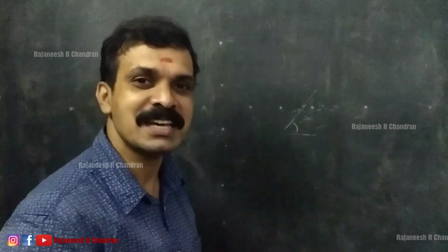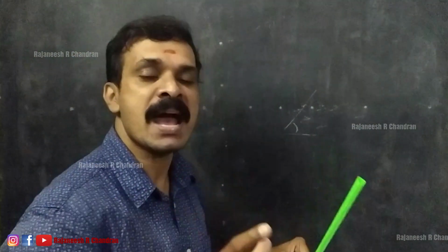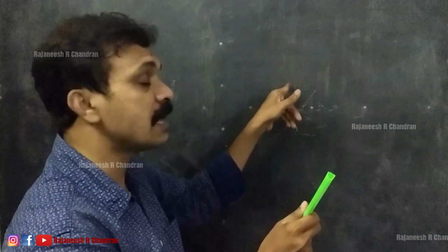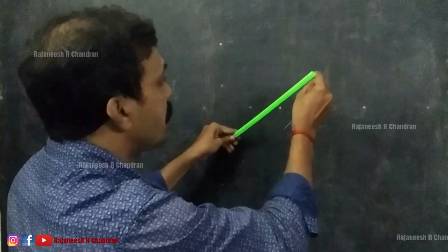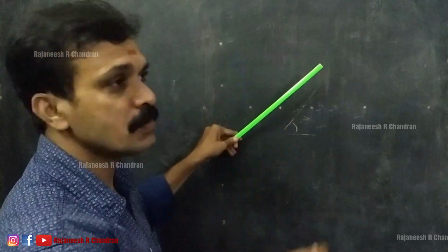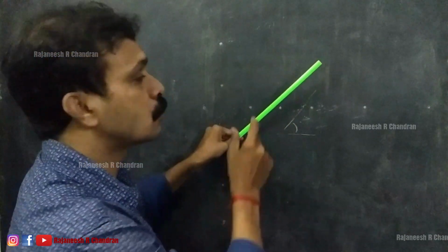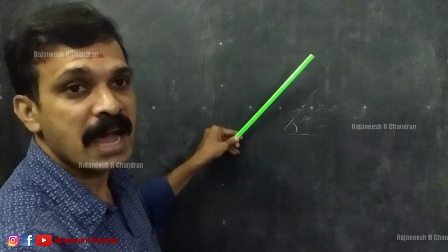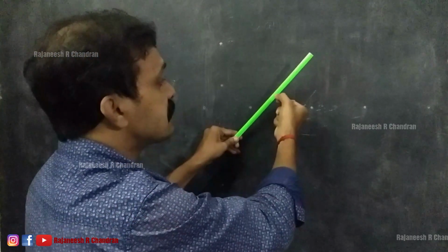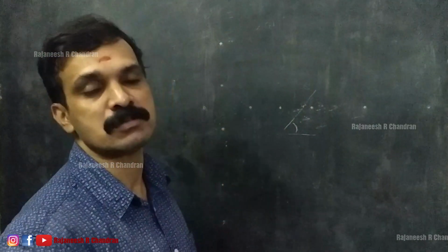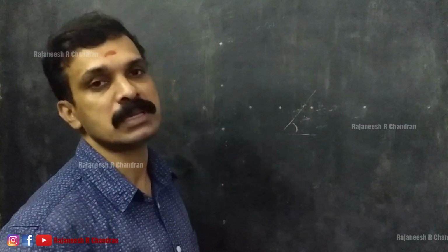And we know that when a line is parallel to one of the reference planes, the projection of the line on that plane will give the true length. Since we made this line parallel to VP, at this point you can see the true length of the line, and since this is the true length, we know that its opposite projection will be a line parallel to XY.